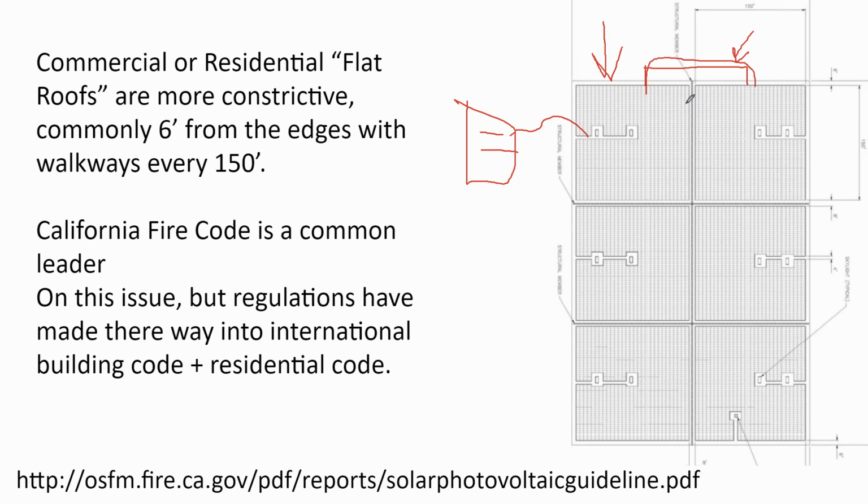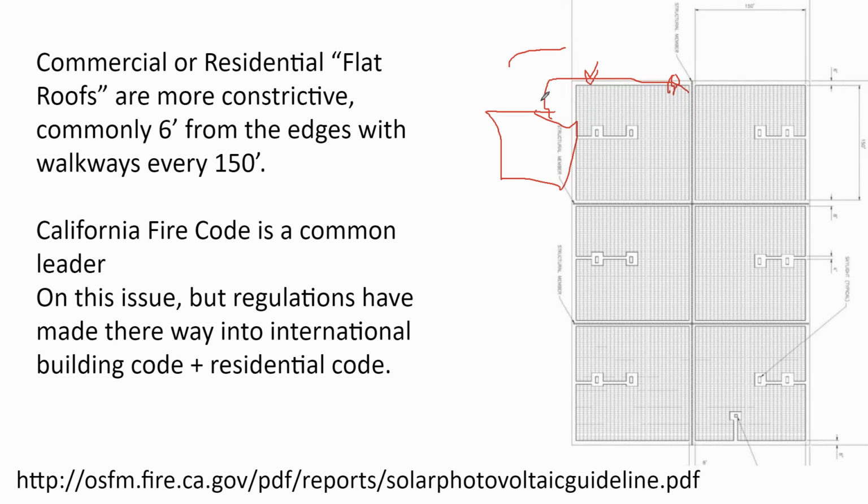You have copper cable inside more like aluminum conduit, and it's very hot, so the cables inside the conduit would expand at a different rate than the EMT conduit itself. And so when this EMT conduit would land on the combiner box, if you don't allow for thermal expansion, which is generally at 120 feet or greater,